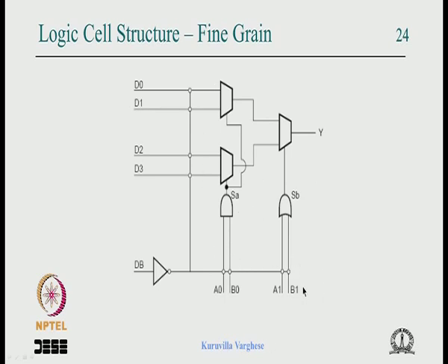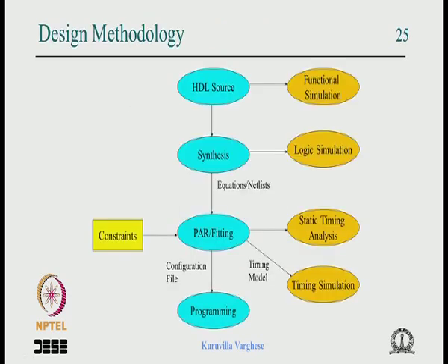So that's a fine grained logic cell of an FPGA. So design methodology, we have discussed this during the VHDL lecture, but then if you have not gone through that lecture for some reason, you are looking at the FPGA part of the lectures, then we will just illustrate that. So the design methodology is currently you start with a hardware description language like VHDL or Verilog. You describe your circuit in VHDL or Verilog.